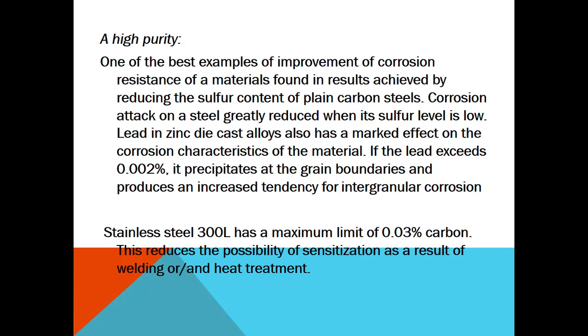Lead in zinc die casting alloys also has a marked effect on the corrosion characteristics of the material. If the lead exceeds 0.002%, it precipitates at the grain boundaries and produces increased intergranular corrosion.